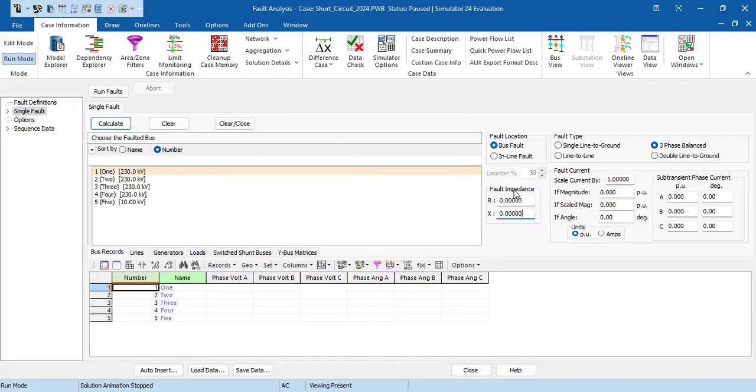The smaller the resistance or the impedance, the higher the current will be, and well, you can tell what's going to happen if the current increases. You're basically dead. So if you could increase your impedance to ground by doing multiple things, it will decrease the current, hopefully to a safe level, hence protecting you or basically anything else. So that's what this is.